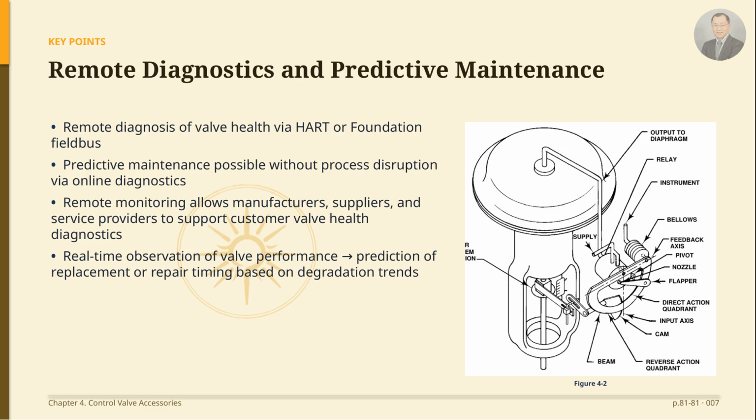Now, it is possible to diagnose the health of a valve remotely via HART or Foundation Fieldbus. Online diagnostics enable predictive maintenance without disrupting the process. Thanks to these remote capabilities, valves can be monitored, and those who manufacture, supply, and service valves can now assist customers in diagnosing valve conditions to a level never before possible.